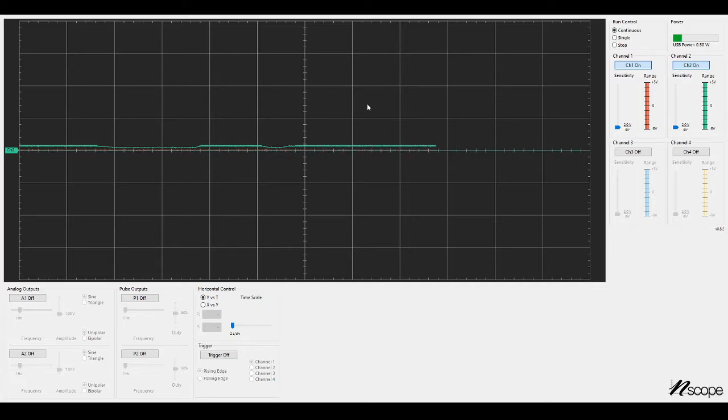Now I'm going to turn on the sine wave. And so it's going from 0 volts up to 1 volt. The LED needs something like almost 2 volts to even turn on. So the LED is not flashing or anything. We just don't have enough voltage yet. So I'm going to increase the voltage coming from A1 being applied to the LED. We'll go to 3.75. This is neat.